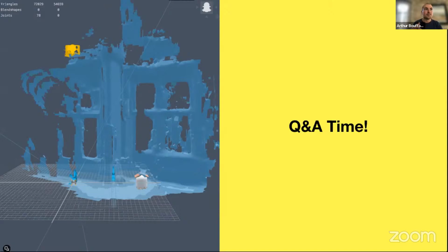And then for something that's 6 to 8 meters tall, I guess, make a photogrammetry model of it. And if you want to get really good scale, also do a LiDAR scan of the building in a different app, and then use Blender to mash everything together and build an occluder for that. I think that's the best approach if you plan on occluding things, and I think that's usually the case.